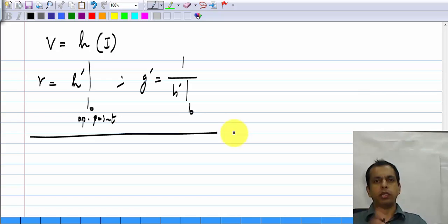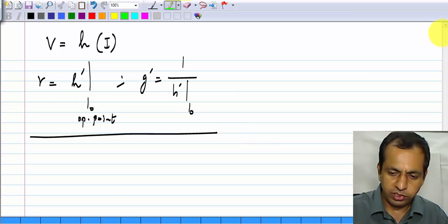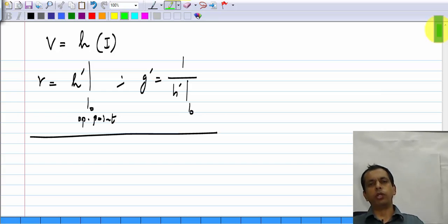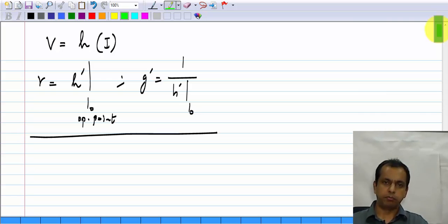So, every nonlinear element can be approximated by a linear element. Now, you see why this method is easier. We do not even need to write the nonlinear equations of the original circuit. You have to do it for calculating the operating point, but from that point onwards, for increments, all you have to do is look at each element and replace it by its incremental equivalent.